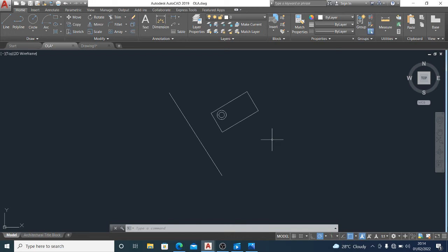I can mirror it to the left side with either deleting the object or still having the object remain on that side. Okay, this is what I mean in essence. So I can click, select the object, then this is the mirror tool. Then I click mirror. Now this plane of reference that I just created, I'll click on it anywhere on the reference line.